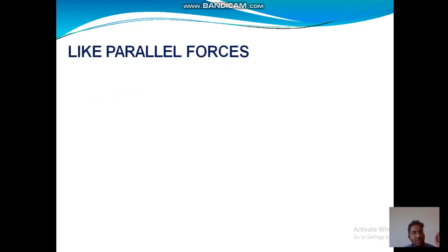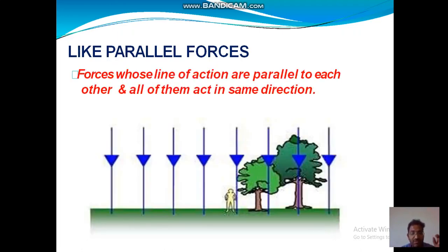And the last ones are like parallel forces. I think everyone knows about parallel forces. All forces are acting in a parallel direction. Why do we add the word like here? It means the forces are parallel and the directions of all forces are also equal, then we can say they are like parallel forces. See the figure here: all forces are in a parallel direction and the direction is also the same, a downward direction.